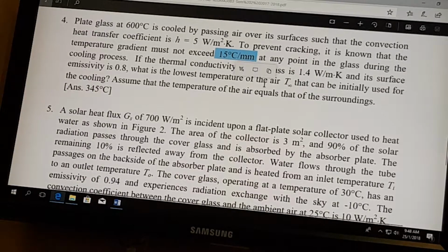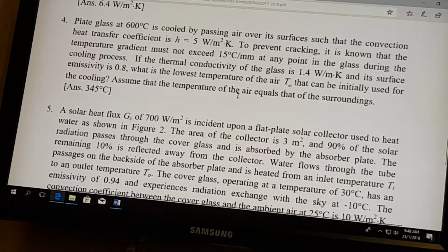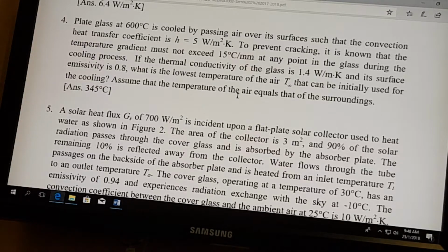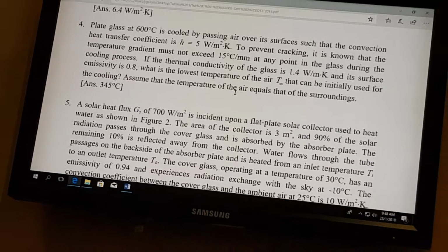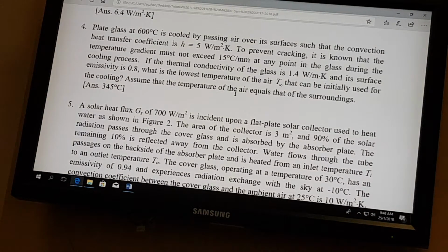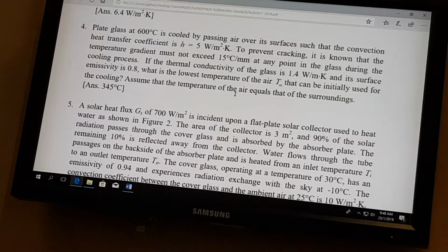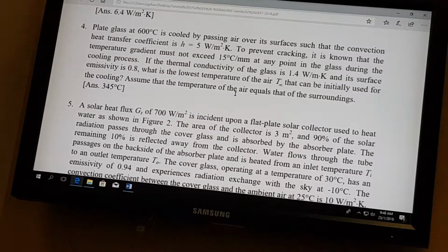So we know the temperature gradient. Actually, it's the maximum temperature gradient, right? Another thing I also need to note: when you do the calculation, it's better to use SI units, Kelvin instead of degree Celsius. But the magnitude of a temperature difference is the same in Kelvin and degree Celsius. When you encounter a temperature difference, it doesn't matter whether you use SI units or degree Celsius, it's fine. But when you deal with just the number of the temperature, we use Kelvin. Better to use SI all the time, otherwise we have trouble.